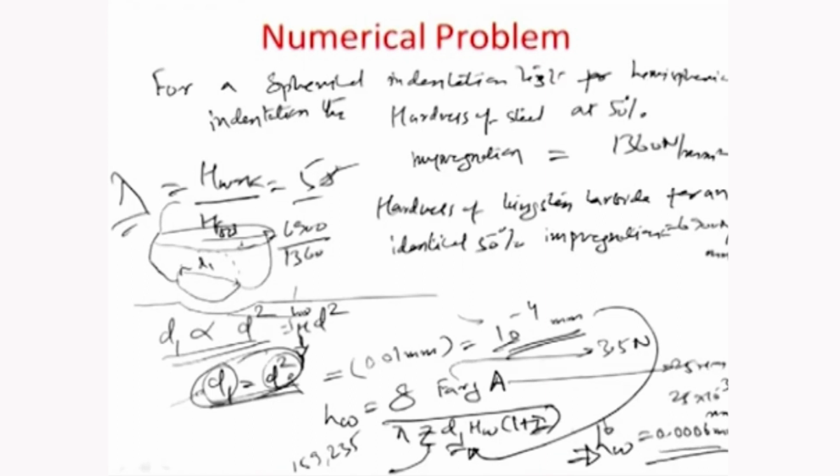So, one thing that I would be very carefully looking at is the magnitude of the indentation that is happening on a surface. So, it is only about close to 0.6 microns. Okay. So, it is not even 1 micron. Which means that the surface finish of such a process is expected to be very, very high.